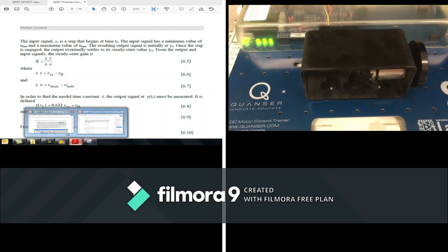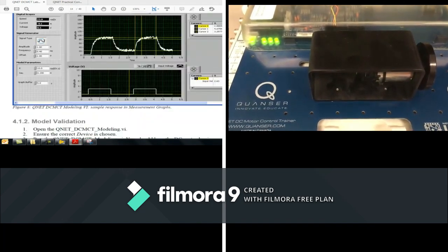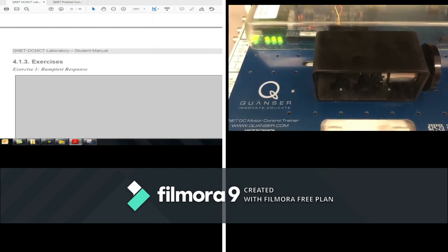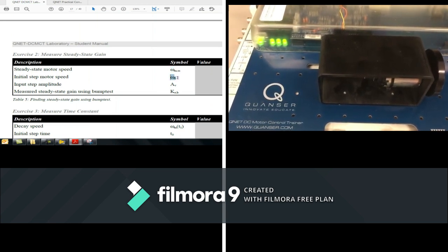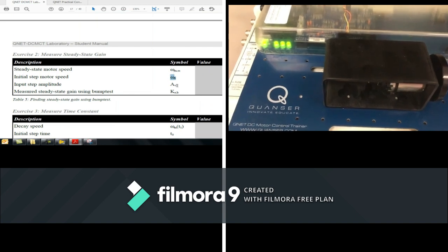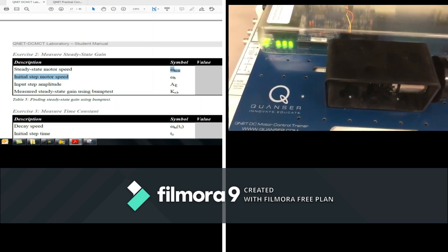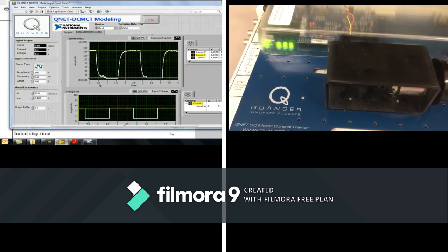If we go back to our student manual, in table number 4, you see now we have our steady state value and our initial value of speed. We subtract them to get delta Y, and we have our amplitude for voltage. If we divide these values by the same formula, we will get our K. How will we do that from the LabVIEW screen?